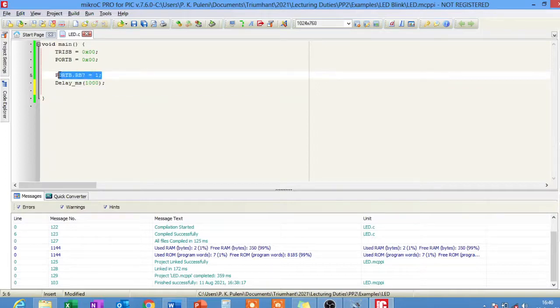So I copy that, put it here, but now at this time it must be off. Turn it off, and then turn another one on. The one that is going to be on is RB6, because we are coming from 7 going up to 0, ne?